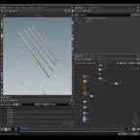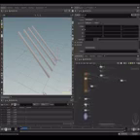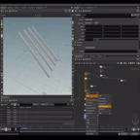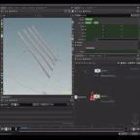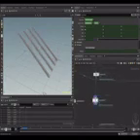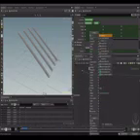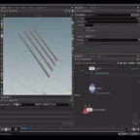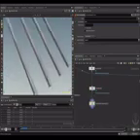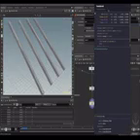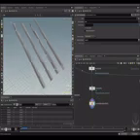Now let's prepare our proxy geometry. So I'm gonna get this transform node, and I'm gonna do the same. I'm gonna create a reference copy just in case we want to increase or decrease the initial rotation. And I can call convex decomposition sub, plug it here. And I first had 27,000 points, and now I have 24, so it's doing something.